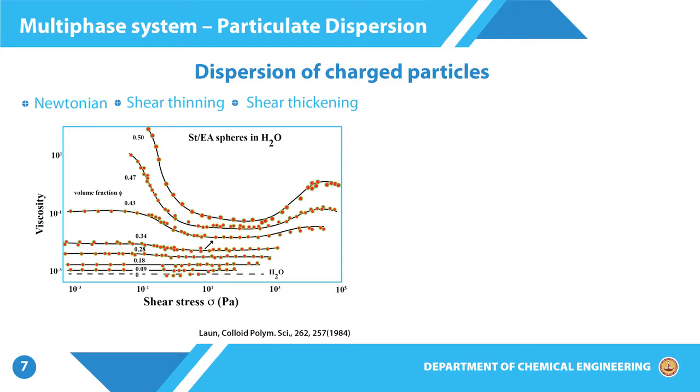So, one of the first things we notice is that if the concentration of particles which is mixed is low, then what we see is a marginal increase in viscosity. More importantly, the viscosity as a function of stress remains a constant value, which means the overall behavior of this material seems to be Newtonian like, even though particles have been added, and with the added particles there will be additional dissipative contributions in terms of the interaction between particle and the surrounding fluid, which is water in this case.